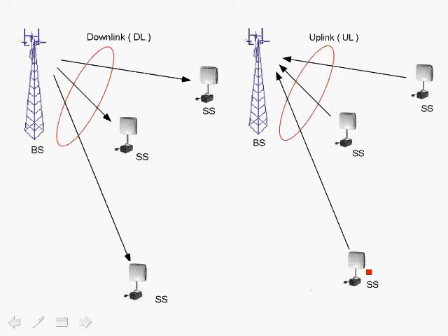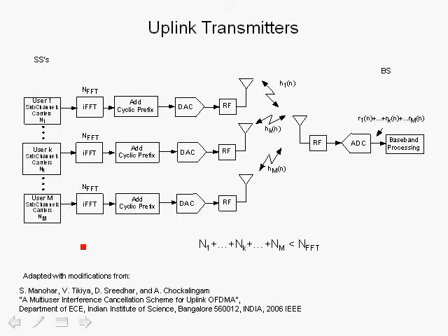The base station therefore can manage the power from the multiple subscribers so as to minimize the multi-user interference from all the subscribers. So in summary, one of the factors that influence multi-user interference within an OFDMA system is, of course, power management. We've discussed that. Time alignment, we've discussed that, where through initial ranging, the timing offset is programmed into the subscriber stations by the base station doing the bulk of the signal processing in order to achieve that.